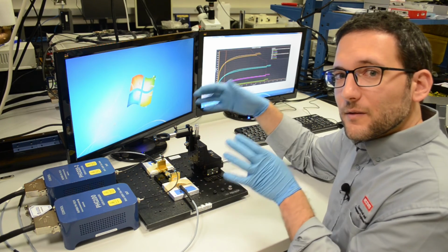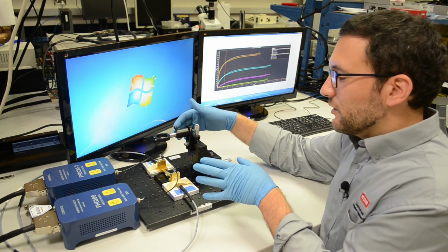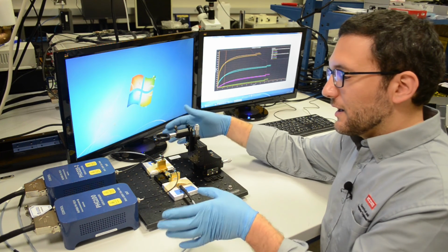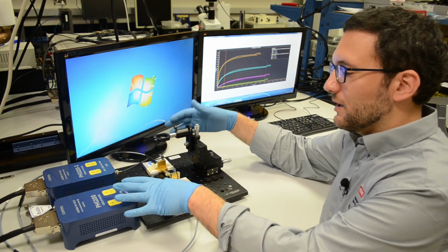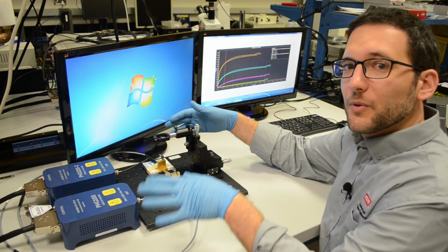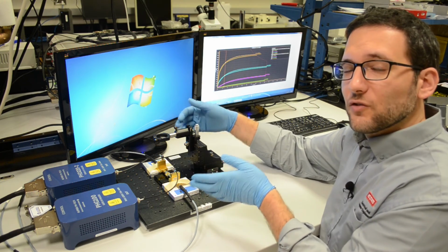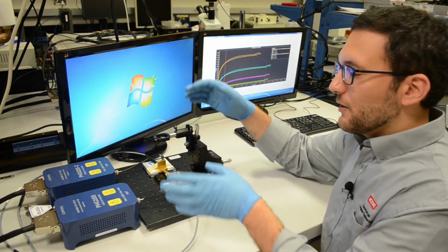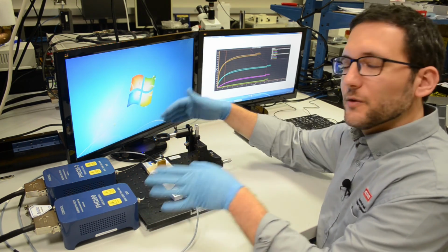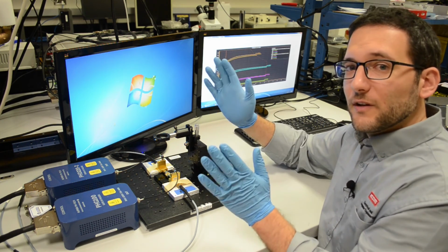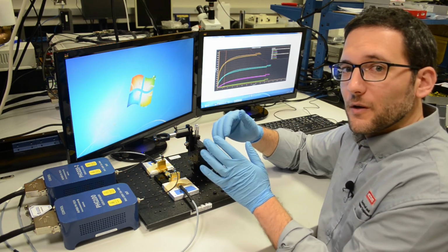In order to test in this particular setup, we've actually gone ahead and wire bonded a very similar AlGaN-GaN HEMT to the one that we saw earlier onto an aluminum nitride board. That allows us to then connect the pulsar heads shown here for the gate and drain, or the input and the output, to the board onto which the die has been attached and wire bonded. The pulsar heads have to be as close as possible to the device itself in order to provide a clean square wave, especially as that pulse width gets smaller and smaller.